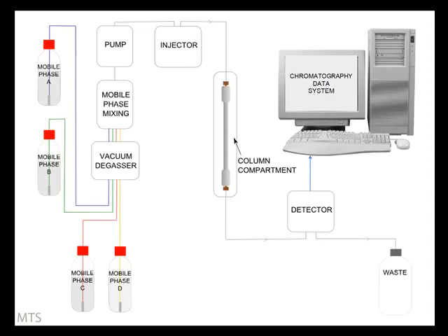So what happens during an analysis? The mobile phase is flowing through the system from the mobile phase reservoir to waste. We will inject a mixture of 3 components, shown here using 3 colours: pink, green and blue. At the head of the column, when the sample first encounters the stationary phase, we have a mixture of all 3 components. The equilibrium between each component, the stationary phase and the mobile phase is different for the 3 colours